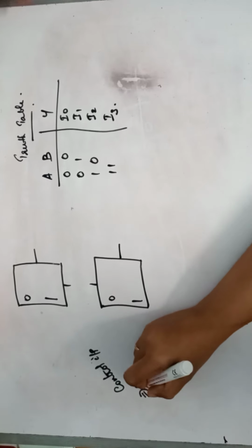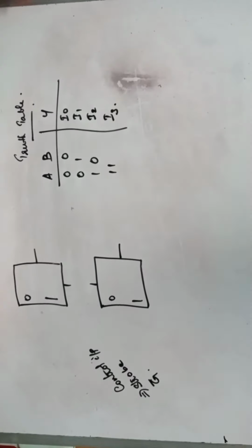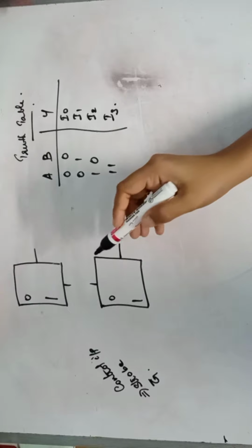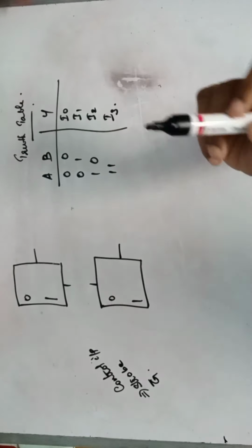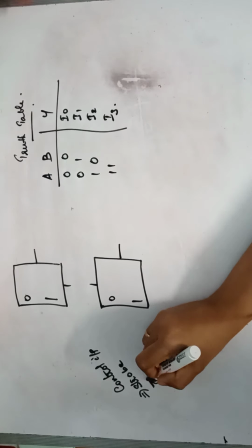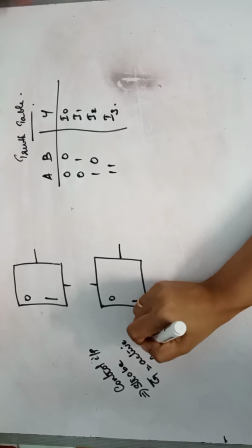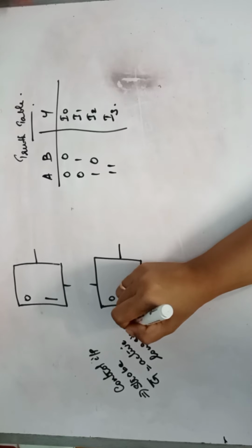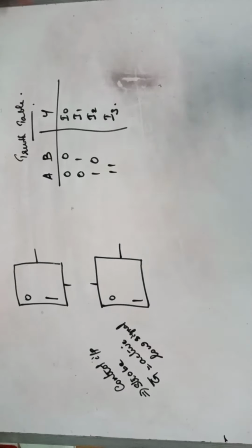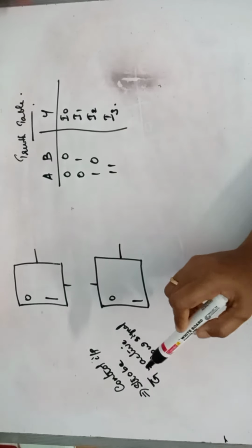And this is called a strobe, which is notated by G dash. Now, what is the strobe? Strobe activates a particular mux IC. That is, when this is notated as a G bar, this is an active low signal. That is, this particular input is active when you give a low to it. Active when low. That is why it is notated with a G dash.